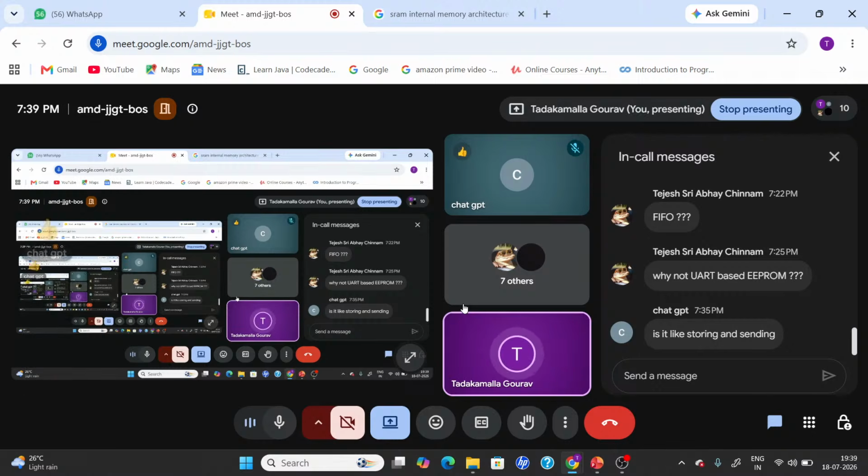And we are not sure about how the buffer is going to program the array cells. It's all the technology that particular vendor is using. It's all proprietary. If you want, you can explore it once, but I'm not sure about how the internal array cells are being programmed from the page buffer. It's completely the internal architecture, and it's an interesting topic which you can try to explore. But from the top level view, you need to know that there is some kind of buffer in between. If you send any particular data, that will be stored inside your buffer, and from the buffer to the internal array cells, it is going to take 5 milliseconds of time. Okay.